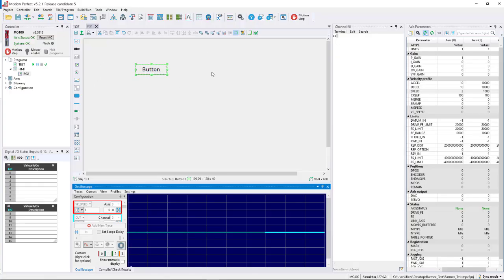You just need to create your project and then download it by using this button. Upload it into the HMI. And once you have the HMI powered on and connected by Ethernet cable to the controller, it will transfer the program through the controller to the HMI. So the controller is just like a gateway because you always connect to the controller, not the HMI directly. Okay.